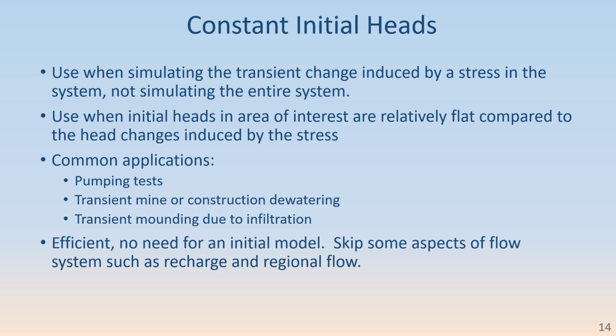The constant initial heads option is often very useful for simulating something like a pumping test or a short transient dewatering situation, where what you're really interested in is simulating the change induced by some stress, pumping at a well or at a dewatering system.